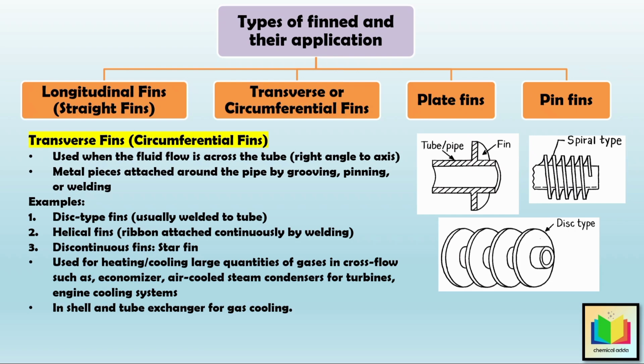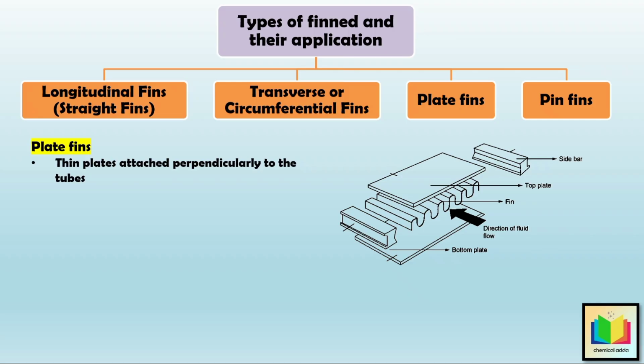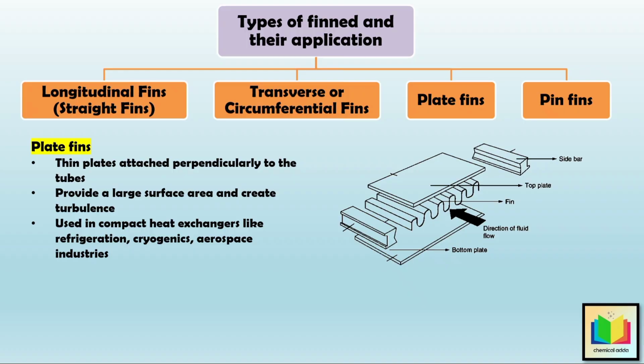Then let's see the third type of fin, which is plate fins. Here, thin plates are attached perpendicularly to the tubes. That's why they provide a large surface area and also create turbulence, which increases the heat transfer rate. Then, plate fins are widely used in compact heat exchangers, like those in refrigeration, cryogenics, and aerospace industries.